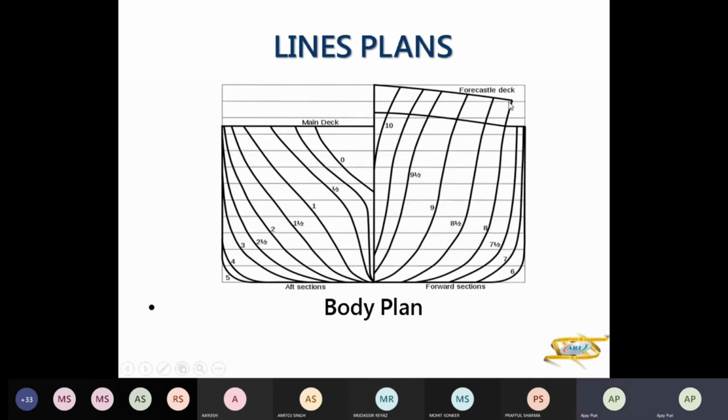So here, as I had explained, the sheer is there. Forecastle is twice the sheer and twice of aft, that's why this is raised. Number 10 is your forward perpendicular and 0 is your aft perpendicular. Accordingly, it's being done here till 5, and 5 and 6 are midship areas, and then the forward curve is coming up, and the horizontal lines are the waterline planes.